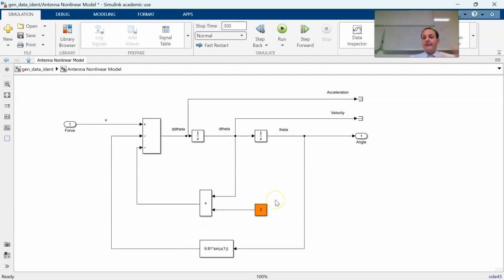It means, in fact, that the moving antenna is subjected to a drag torque, which depends on the angular speed, and then we have the dependence on the position, which affects, of course, the weight, the gravity, the weight of the antenna, and the main forcing input, represented by the force that, for example, can be generated by an electric DC motor, depending on the specific application.